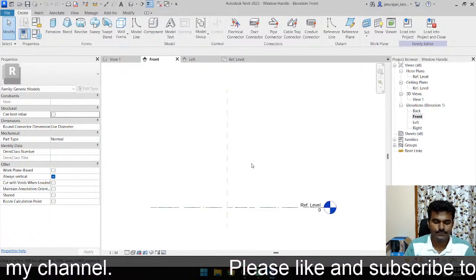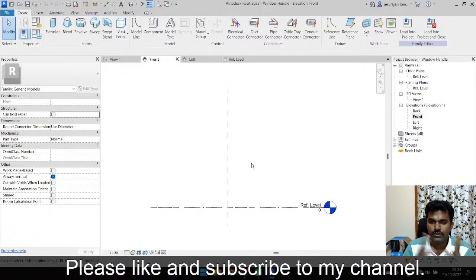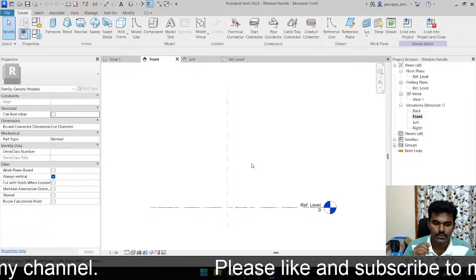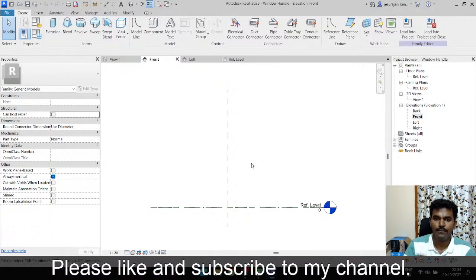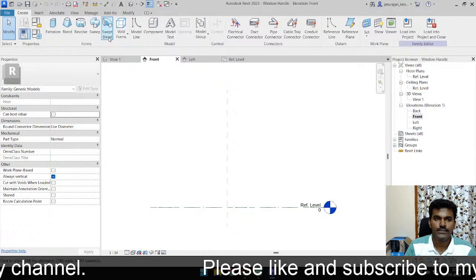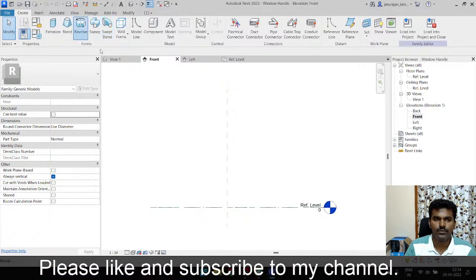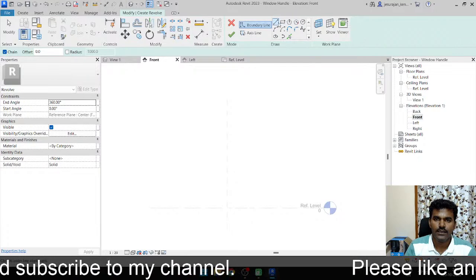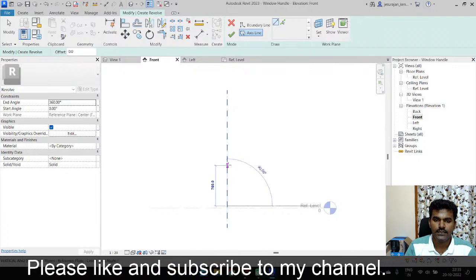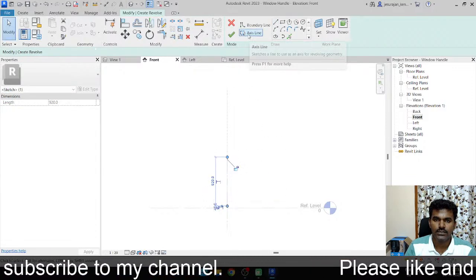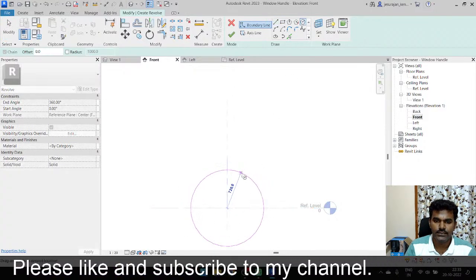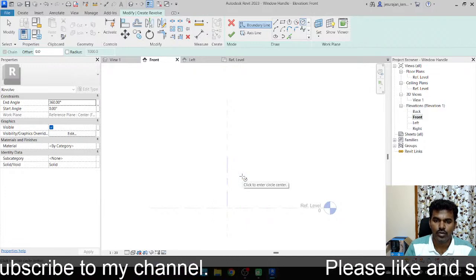Okay, so here I'm thinking, you can have many designs. The door handle, what I'm going to make, is going to be kind of a bulb. So I'm going to take swept blend. Oh, no. So I'm going to take a revolve, and I'm going to take axis line and just select this boundary line. And here you can see, that's a door knob.